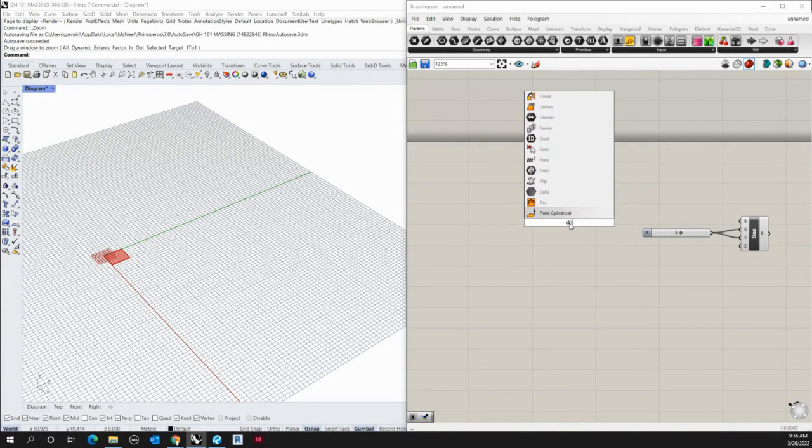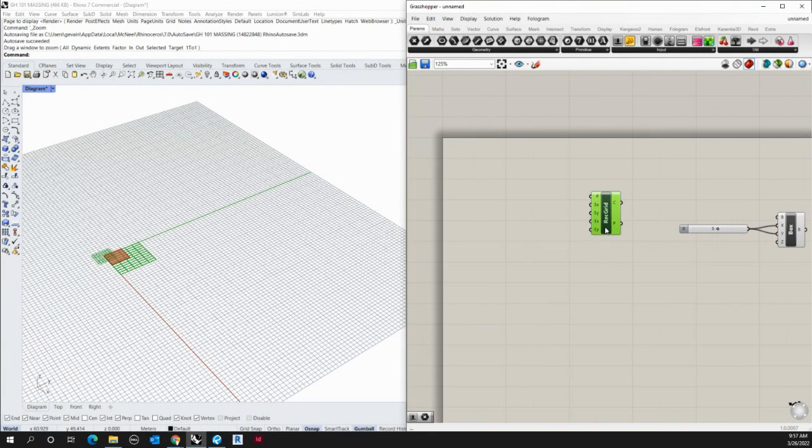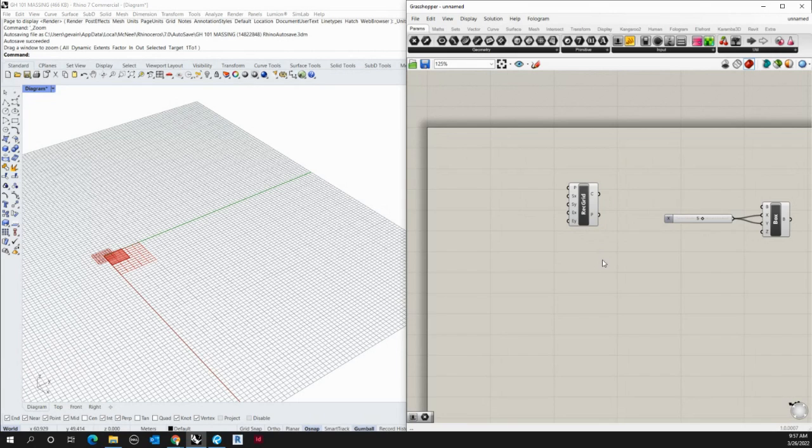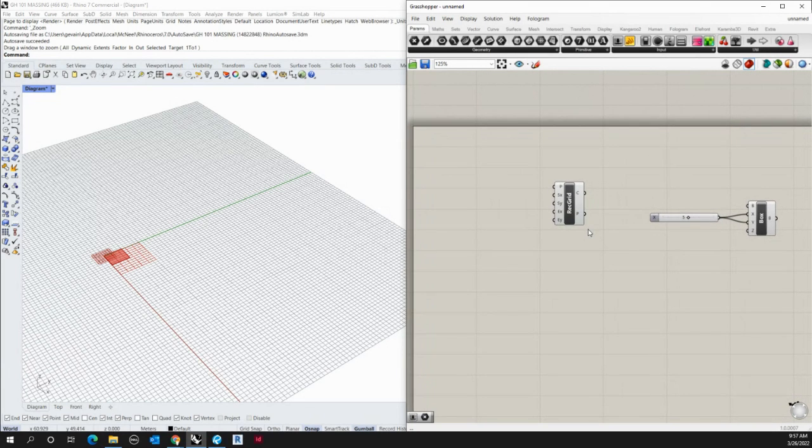So if you double click and search for grid, unfortunately, you won't find anything. And that's sometimes the limits of this search tool. You kind of need to explore and find stuff. And that's how you discover new things once in a while. But the actual tool is called rectangular grid. And that's a weird one because it actually doesn't even say rectangular grid. It just says rectangular. So that's the kind of thing you need to dig in a little bit and find, unfortunately, or just ask people that have done that in the past and what they used.